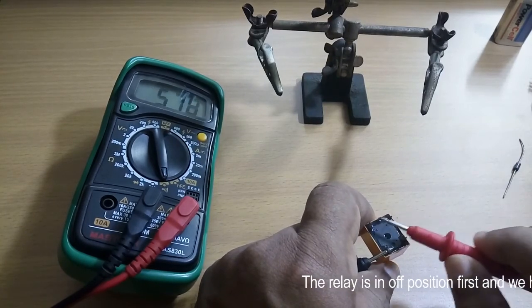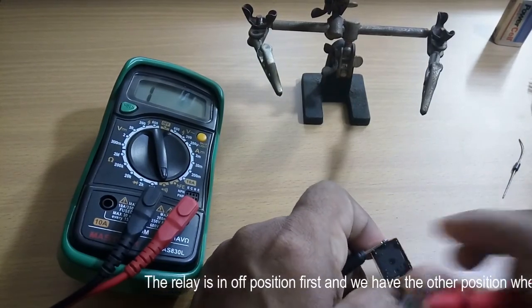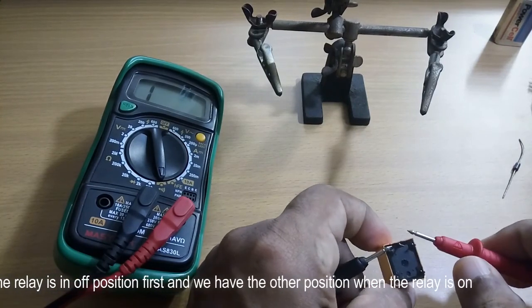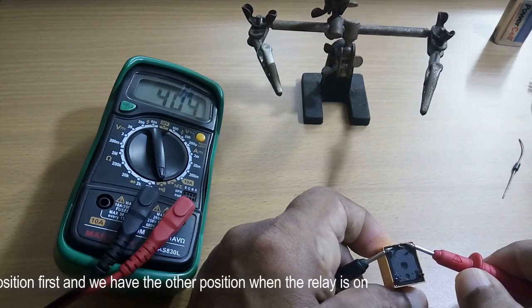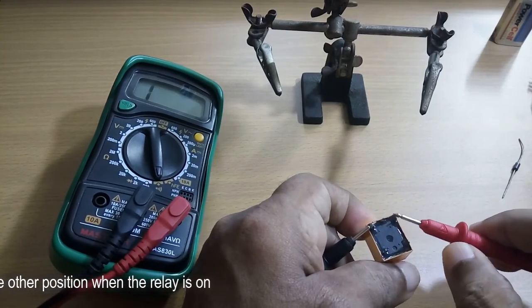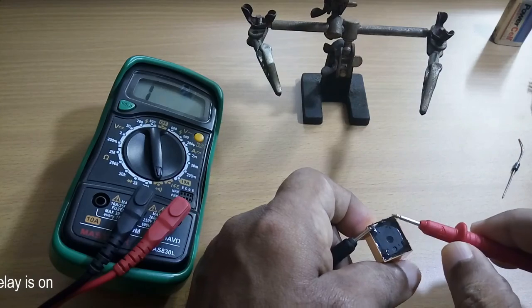It is directly connected when the relay is on. And we also have the other position where the relay is off. This is not connected, and this seems to be the inductor, the coil inside. The coil is showing 400 ohm impedance.